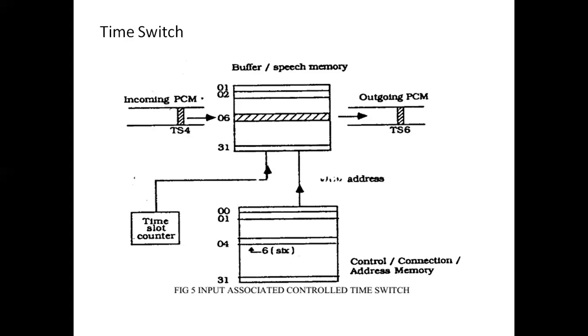If I am the switch operator and I want to transfer the present time slot 4 to time slot 6, which comes later in time than time slot 4, you need to wait till the instant of time when the transfer of time slot 6 occurs. Remember, time slot 6 occurs later than time slot 4.